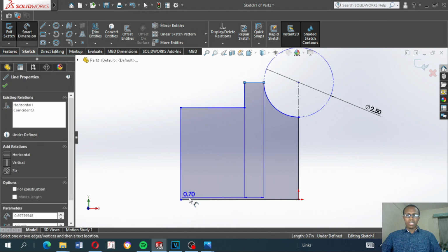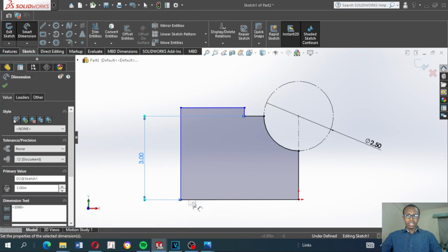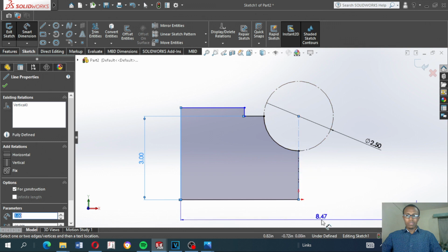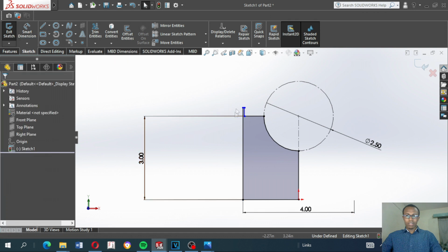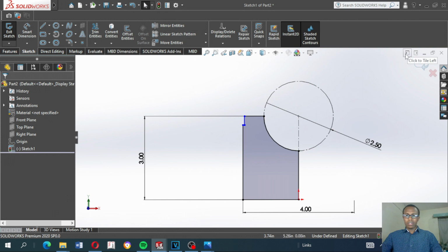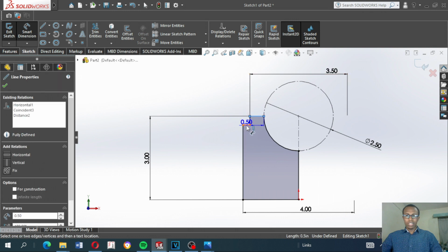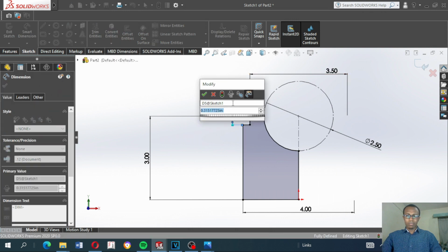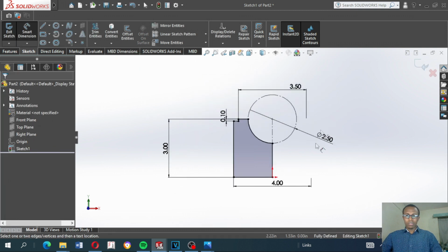As we've seen, our total height for this object will be 3 inches. Our diameter will be 4 inches. Now let's pull that down. Let's just confirm. Then the diameter for this part will be 3.5, and its height for this step will be 0.1. And with that, we are ready to revolve our part.